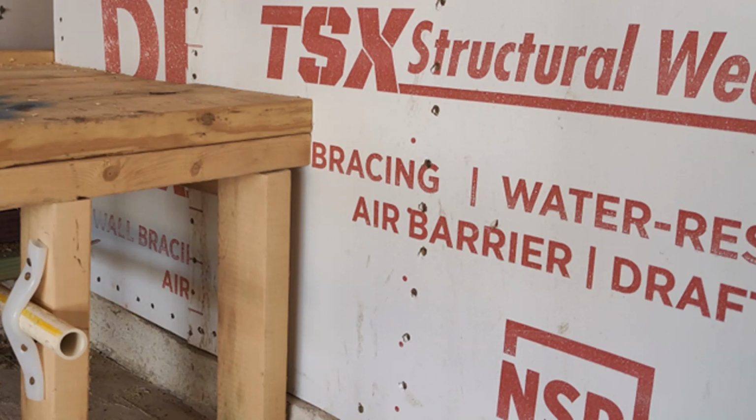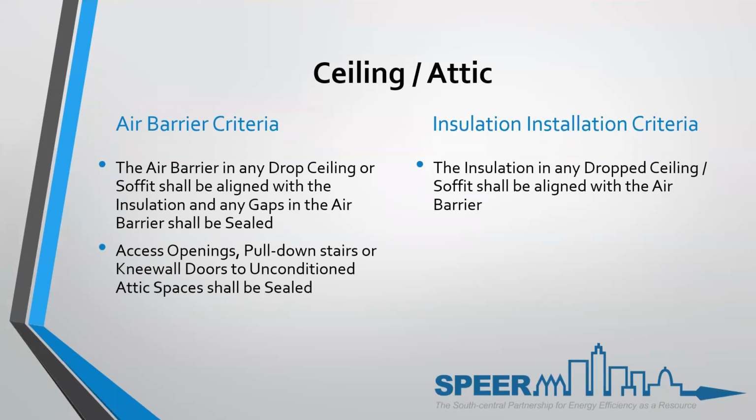There should not be elements of an incomplete air barrier or incomplete air sealing from garage to inside. Just because it specifically calls out a garage wall, that garage wall is still an exterior wall. When it comes to a third-party energy verifier, they will see this wall as an exterior wall and try to treat it as such and call out any deficiencies in that. And we'll talk about that more when we get to the garage separation category.